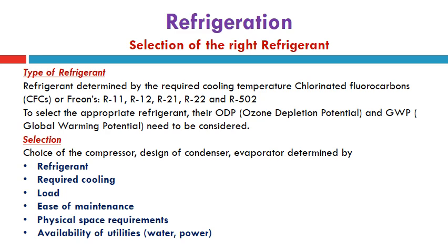Also, the power to be provided to drive the refrigeration circuit must be taken into consideration, and its initial cost requirements and running cost requirements should be considered, and a break-even analysis should be made on the cycle. All of these parameters will be based on the type of refrigerant that you have selected to carry the load and act as the working fluid inside this refrigeration cycle, especially one based on the vapor compression cycle.